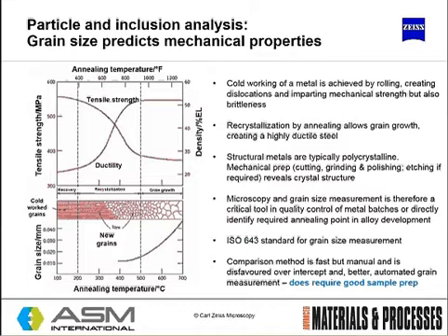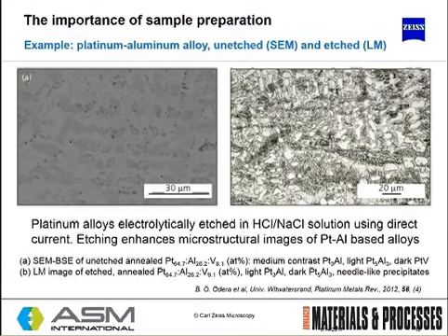And there are different methods to do this. There is what's called an intercept method of measuring the grains in a single line, a comparison method, which is very fast, but it's manual, which uses comparison charts. But even better, there is automated grain measurement, and the modern light microscope is able to perform a huge variety of analyses and measurements automatically. Just as an aside, that does require good sample preparation, and this mustn't be ignored.